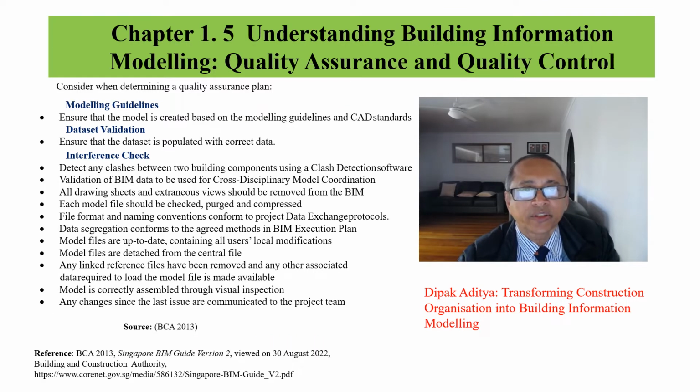BIM quality assurance and quality control. Follow modeling guidelines, dataset validation, and interference check. Detect all clashes using clash detection software. Check if the model file is up to date and if models are correctly assembled, and any change in the model since the last issue.